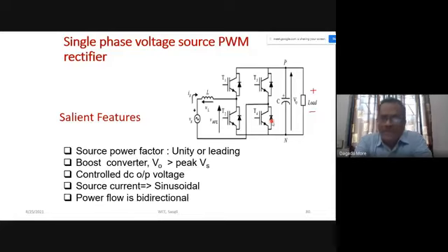Here in the diagram we have shown IGBT. And we have shown 2 passive components in the circuit, one is an inductance and the other is a capacitor. So what essential circuit components do we require? We require 4 fully controlled switches, maybe IGBT or MOSFET, and 2 passive components. At the input side we require an inductor, and at the output side we require the capacitor.